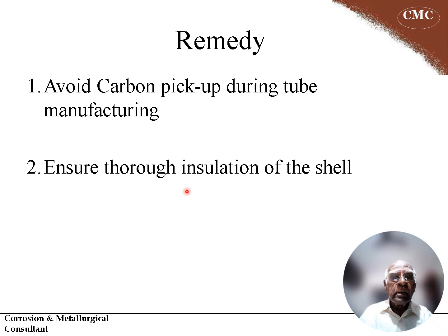Whereas at that particular location on the shell side, the insulation was not done, because the whole exchanger is under support. The supports were not insulated, so the support took away the heat, leading to condensation, and that condensation has resulted in corrosion.